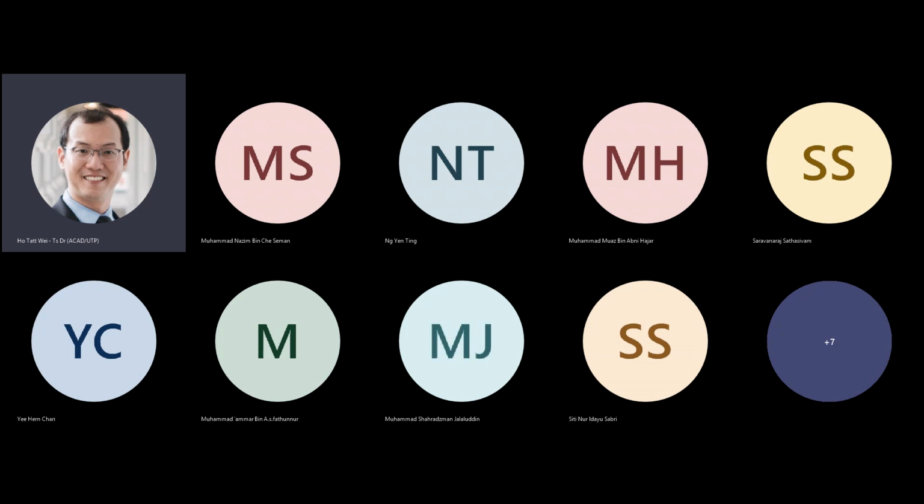So the first step would be we would try to write the truth table. So this is the input and this is the output. The truth table is just a mapping of the input logic levels to the output logic levels. For a NOT gate, input of 0 will give logic 1, input of 1 will give a logic 0 at the output. Logic 0, of course, is ground, and logic 1, of course, is VDD. So for the NAND gate, you got two inputs, input 1, input 2, and the output. So you get 0, 0, 0, 1, 1, 0, 1, 1.